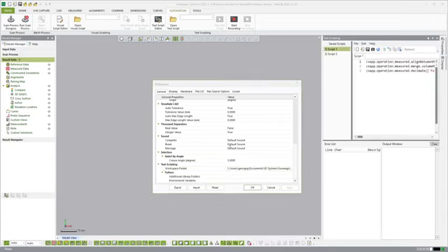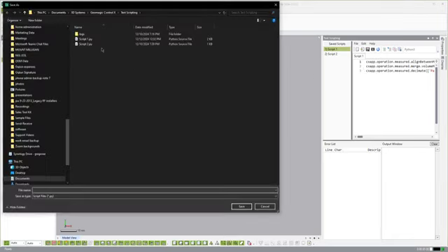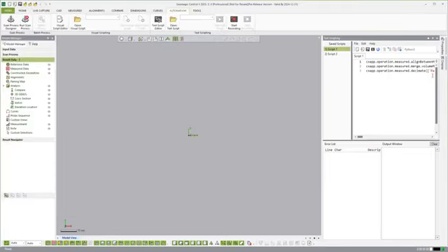And if you want to see where all of the scripts get saved, you can come over here to textual scripting, File, Save As, and you'll see that it is in your documents, Control X, text scripting, and then the scripts are located there, and they are ASCII text files, obviously. That's where the location is.